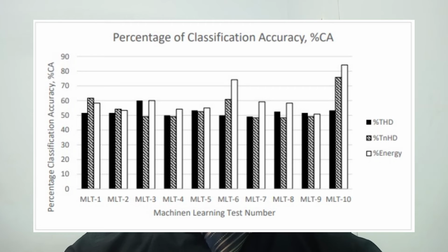Okay, overall there are 11 samples including the control sample. Each sample will be chosen one data. The data chosen must have the highest THD value among the other data. It is because the THD value shows that leakage current happens on the sample. So to achieve the objective of this study, a high THD value is required in this classification of leakage current. This graph shows the percentage of classification accuracy for each parameter between the unlabeled sample and the control sample.